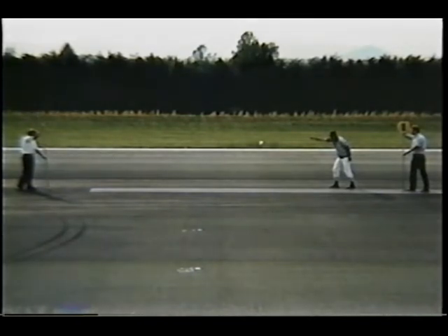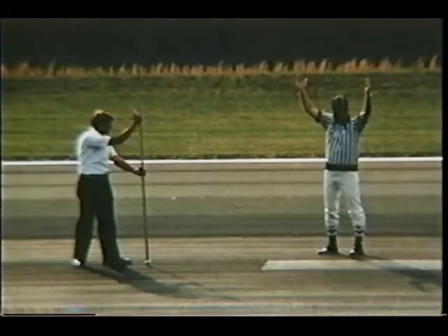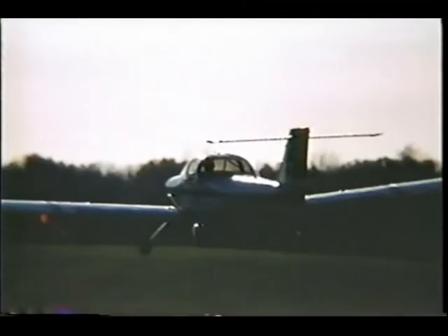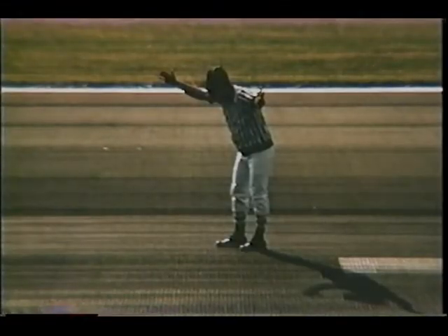If the proper approach speeds have been flown and your piloting techniques and procedures were on target, your point of touchdown will be right where you intended it to be. That is, at your intended point of touchdown. If, on the other hand, your piloting techniques and procedures are still on the money, but you happen to be carrying excess airspeed at the moment of flare, your airplane will float, continuing to glide above the runway until that excess airspeed has dissipated. As a result, you will overfly the intended point of touchdown and land long.